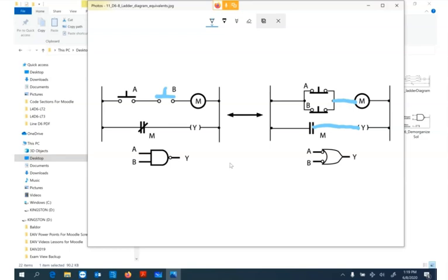So the two switches in series are the NAND instruction. The normally closed contact is our inverter gate. So if we push A and B together, our output will go out. Right now our output is glowing, or on. Now when we look at the opposite, our coil right now is energized, so that means this instruction is true, where our light is on, same as over here.